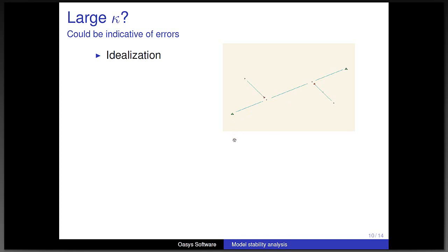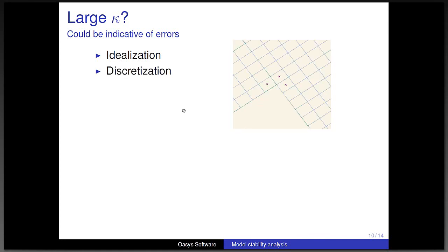Now, in the physical structure, this might be stable, but in your finite element model, this wouldn't be stable because the primary beam is free to rotate about its axis because it doesn't have any rotational restraints coming from the secondaries, and also because it's pinned with supports.